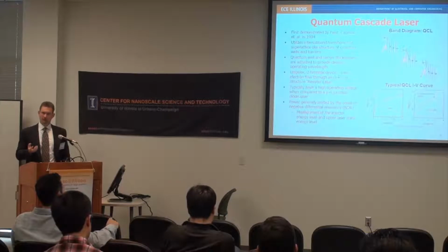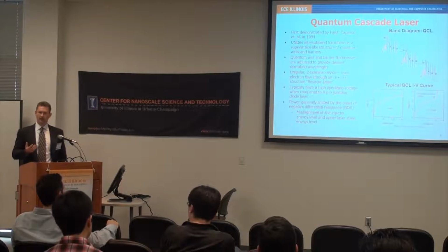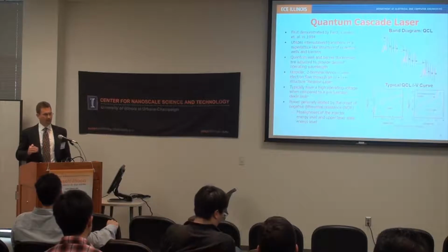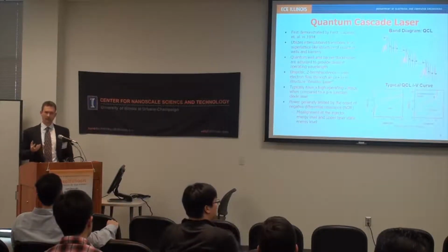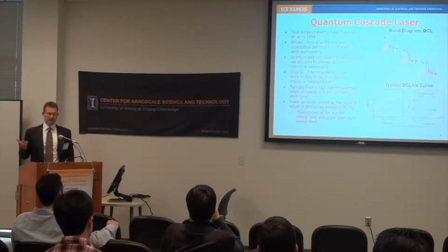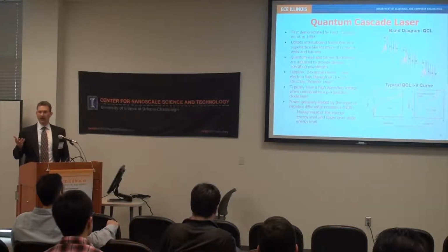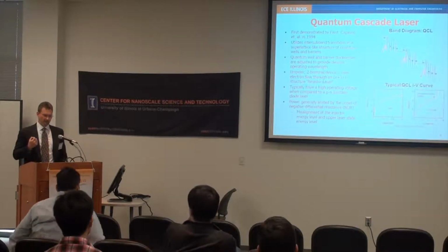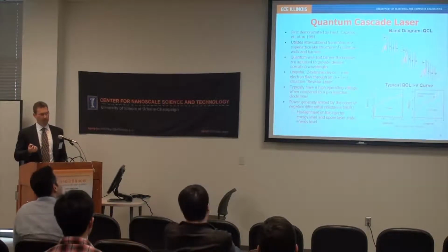And we also are working with fundamental properties such as state recombination lifetimes. By varying the quantum overlap between one state and the next, you effectively are able to vary or control the time that a recombination event is going to occur. So unlike a semiconductor laser or a band-to-band process, where we're sort of stuck with what we have, in the sense that we can vary our quantum well thicknesses and things like this, here we're actually engineering the physics. We're using physics to engineer the recombination process itself.